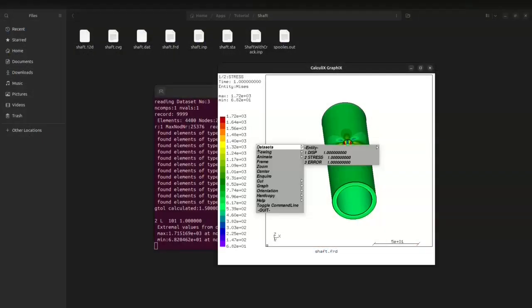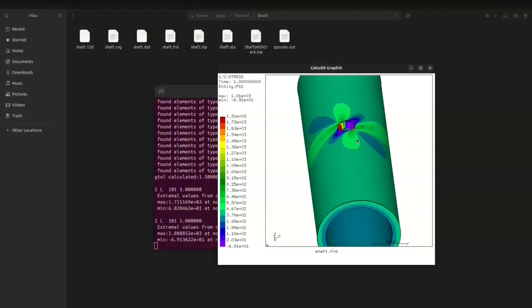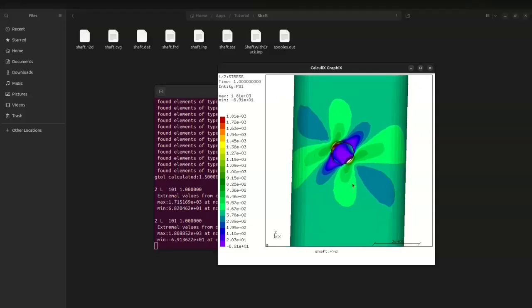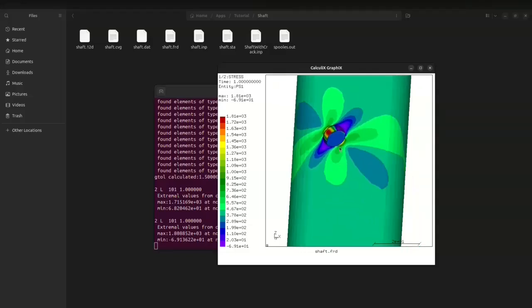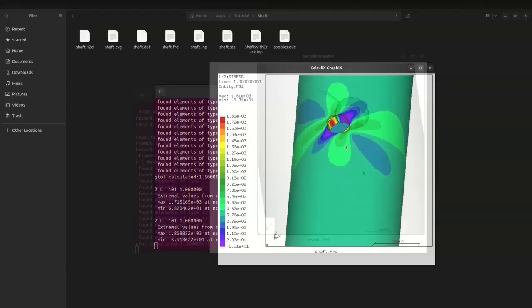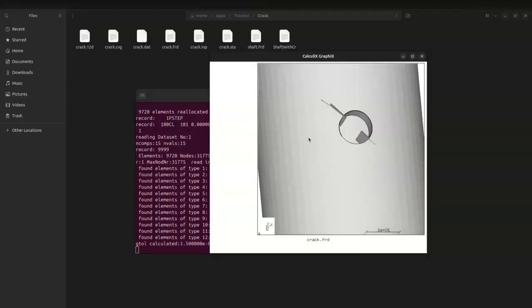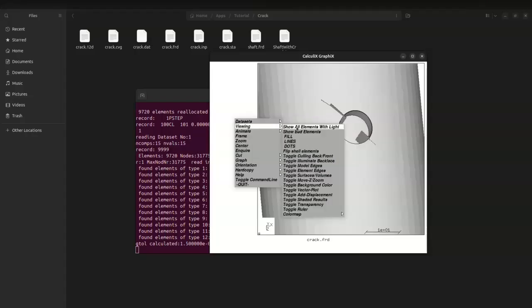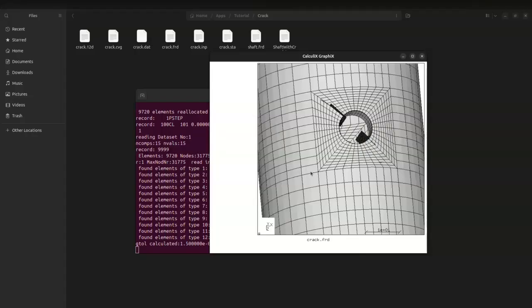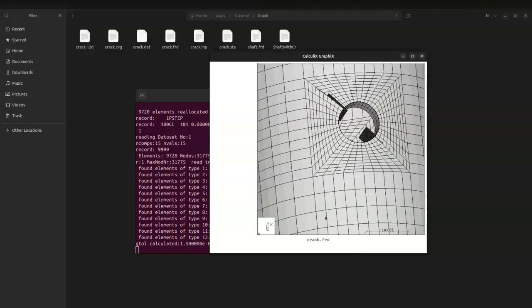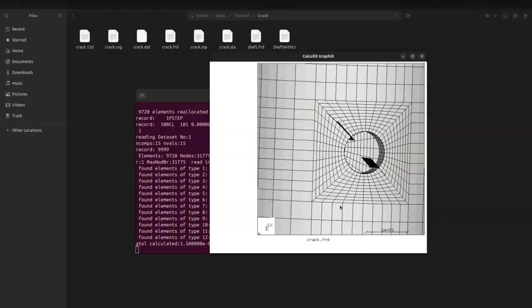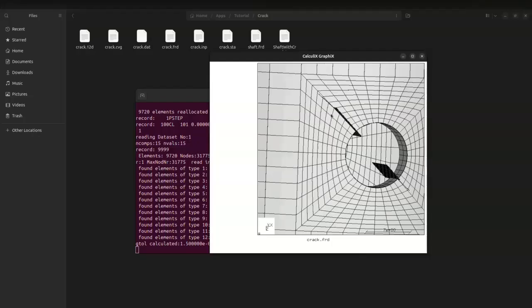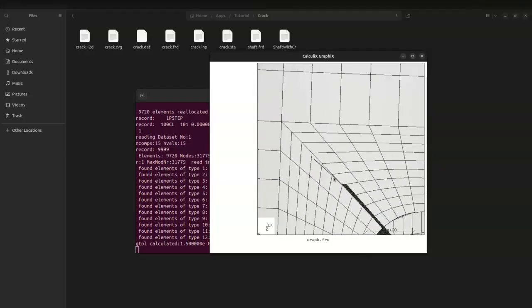We notice that the maximum stress is roughly inclined 45 degrees in the hole and the maximum principal stress is exactly aligned with the crack. So we see the result. There is a crack propagation. We also see that the crack is getting deflected depending upon the stress field.